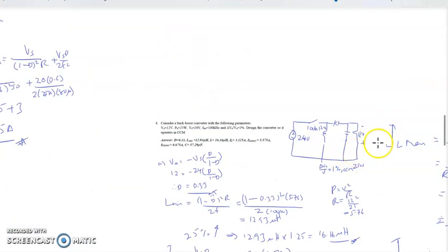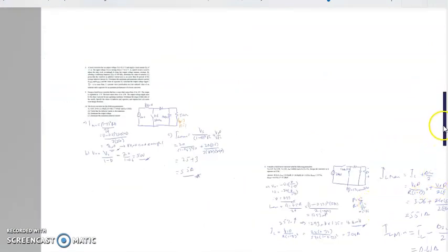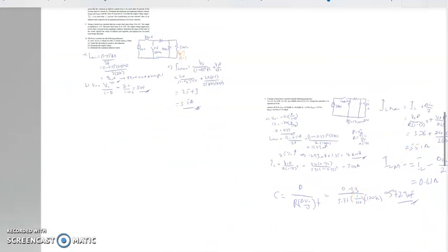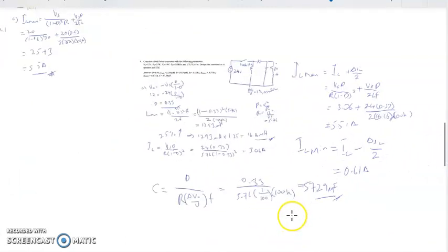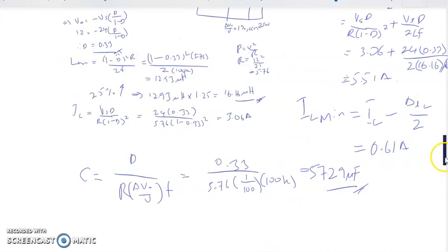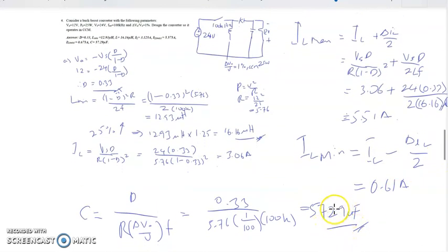So actually in our catalog, there is no such value as 557.29 like that. So this is the minimum. So we can choose any, 560 microfarad or whatsoever, such that it could provide a better regulation in terms of voltage regulation to the circuit. So there will be no such values like this. So you just find the nearest value, which is the next bigger size, to accomplish your circuit. Okay, that's for question number 4.